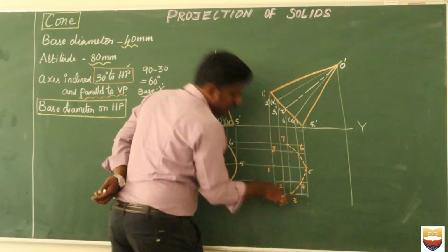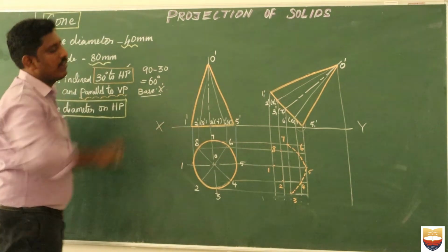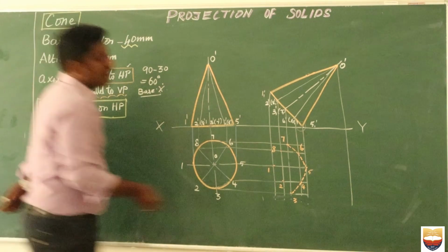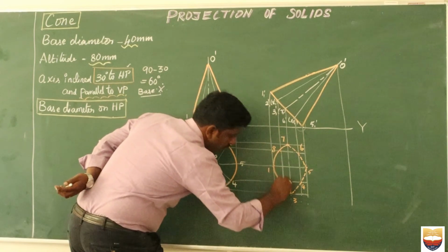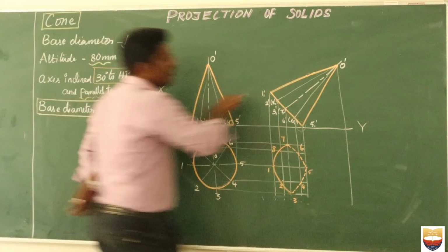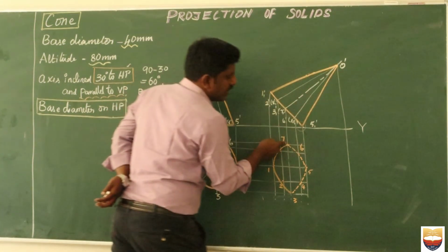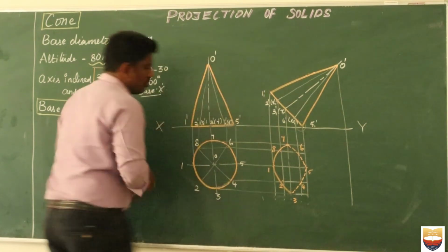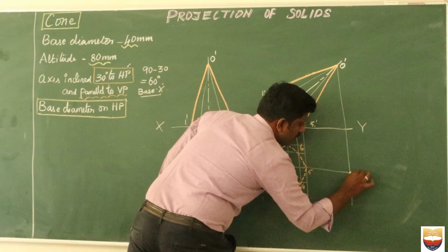So to draw this curve, you can use your French curve. So using the French curve, we may have a curve shape in which you can try to join all these curves. And finally, I am trying to complete the particular portion. As I told earlier, we know that only the outermost part will be darker. You can see the 7. So I forgot about the O to project the O here. So this is our O point. So this is our point O.